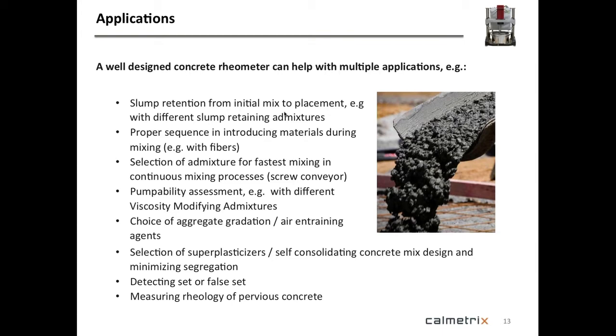As you know, pumpability is an issue in many instances. Of course, when you have a high rise, for example, you would use concrete that is typically very high strength, and it has a low water cement ratio, so it is more viscous, it's stiffer, and it's a problem for pumpability. So you need to help with admixtures, or you need to help with other means, but it's not just adding water, because that will ruin your strength. So here you could study all this.